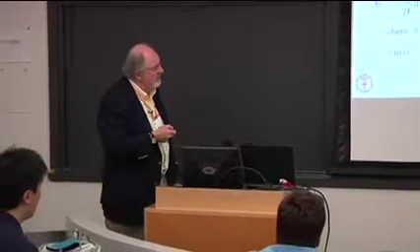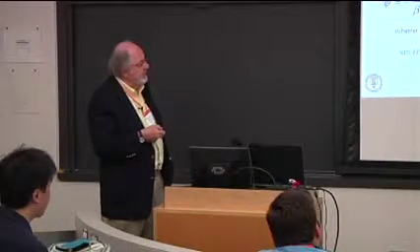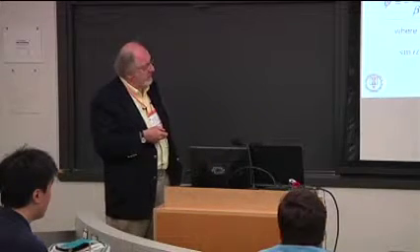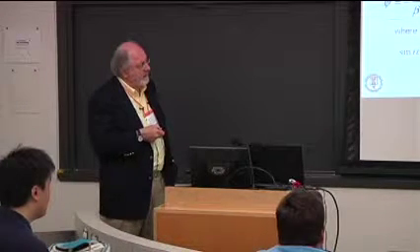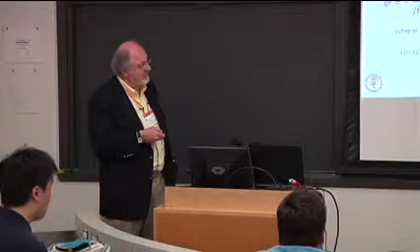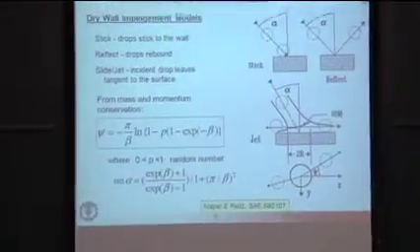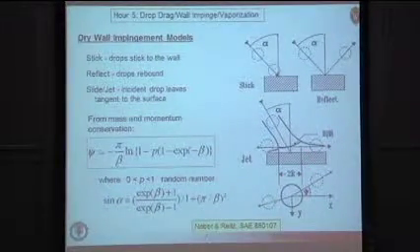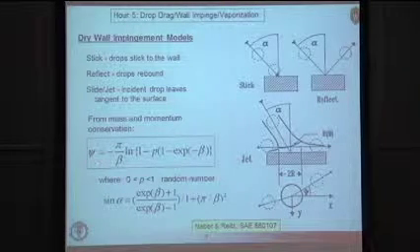So for a train of droplets, to try to account for that, we developed a theory that basically considers the mass and momentum of the stream of droplets directed at the wall, and then a conservation analysis of the mass and momentum in the azimuthal direction to determine how much of the liquid actually flows opposite to the direction of the incoming jet.